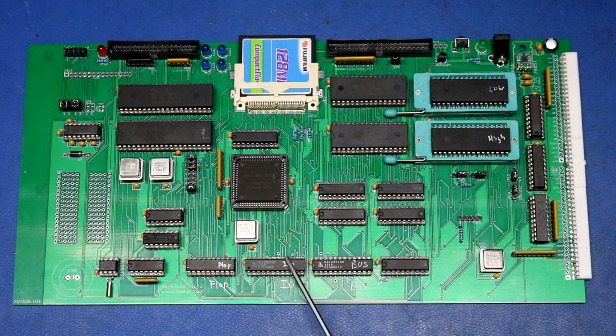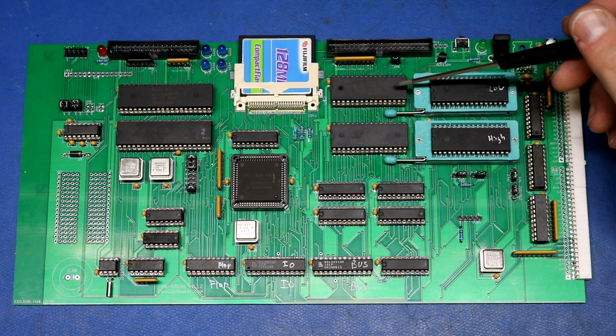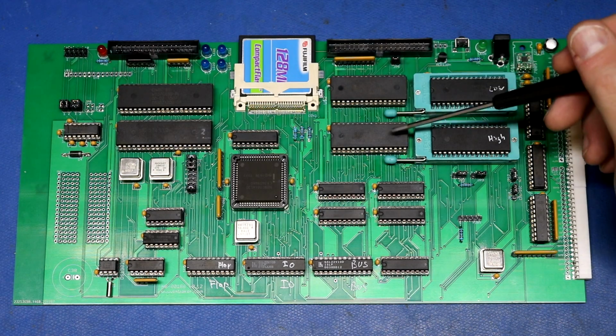We have 3 programmable logic devices that handle our bus logic, some I/O addressing, and then some additional I/O addressing for the floppy adapter. Our memory devices are over here. So a total of 2 ROMs. These are 39SF010 ROMs. They're actually flash chips. They're just what I had in my junk box. Next to the 2 ROM chips are the 2 RAM chips. Those are AS6C4008. Those are each 512K. Together they'd give us a megabyte.